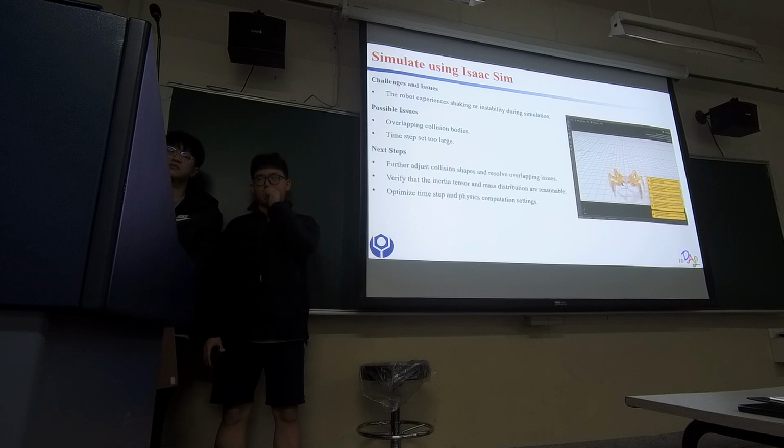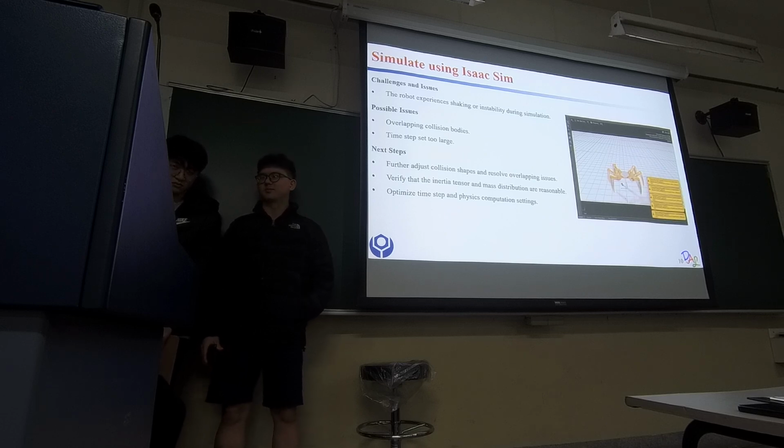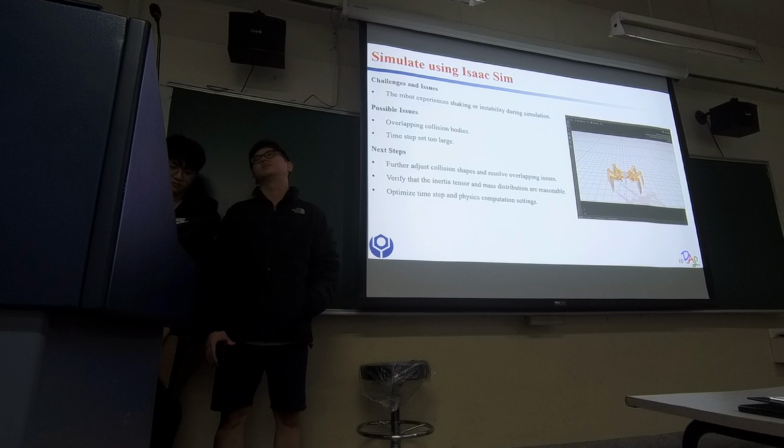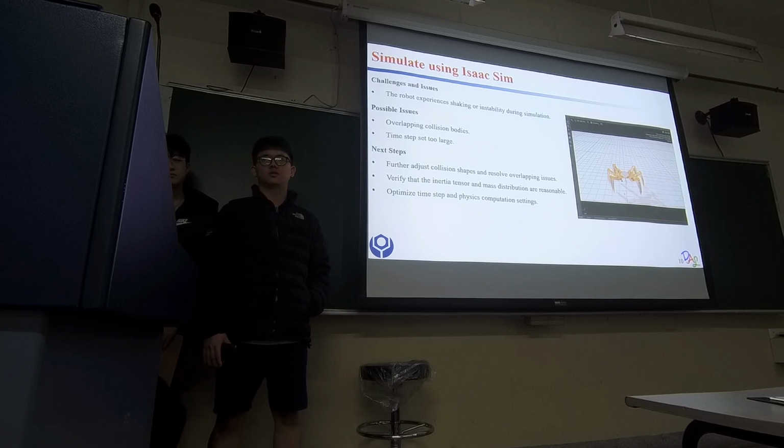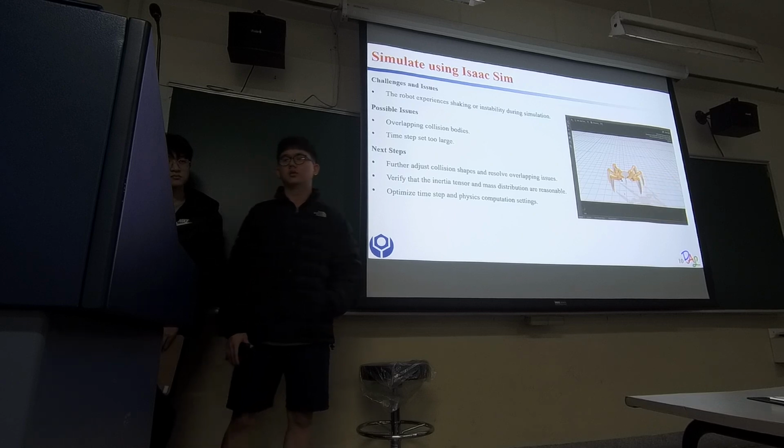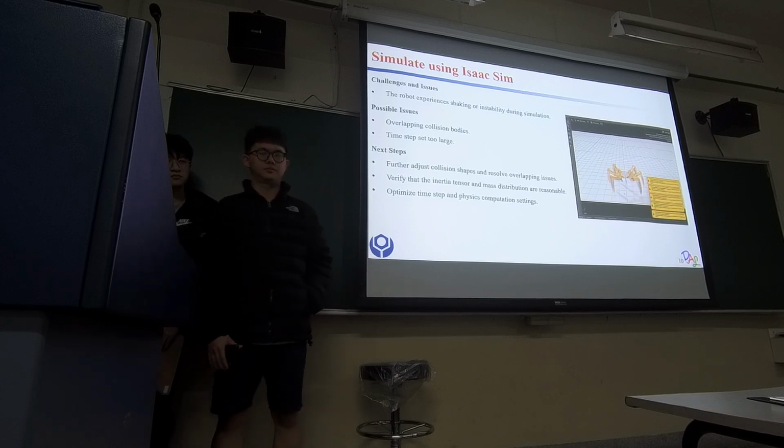So here are our next steps, to try to fix this problem: we will further adjust collision shapes and resolve the overlapping issues, optimize the time step and physical settings, and verify the inertia tensor and mass distribution are reasonable.